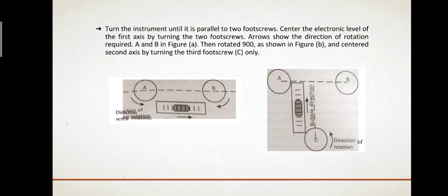So today we talked about the uses or applications of total stations, and how to set up the instrument. The process here is a little bit lengthier, but if you do the rough leveling properly, then the foot screw leveling and other centering will become very easy and fluent. That's all for today. Thank you.